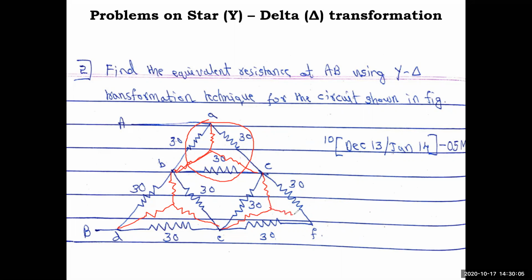So your intention is to do the network reduction, not to apply the star delta transform. Okay, so this is how it looks like now. So now between A to B, you have to look at which are in series, which are in parallel. You have to do the calculation. So this is the first step. If you understood this, next is easy.